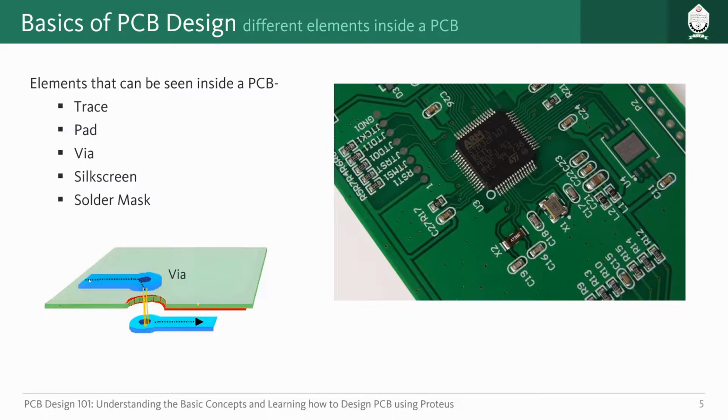We can just take a single core wire, as we see in a resistor, the legs of resistor. We can take that and place that here between these two holes, right? And solder here and here. So it will then connect the top layer trace to bottom layer trace. So in this way we can connect all the vias.